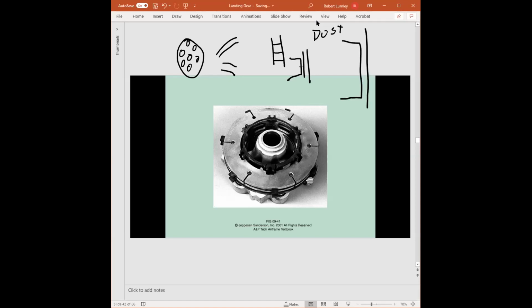When the pad goes in against the disc, it's going to trap air in between because you've got two perfectly flat surfaces. Now, when you heat up air that you've trapped, guess what it wants to do? It wants to expand, so it reduces the friction between the pad and the disc. By having the slots and the drilled holes, the air now has a place to compress inside the disc. So there's more contact between the pad and the disc.